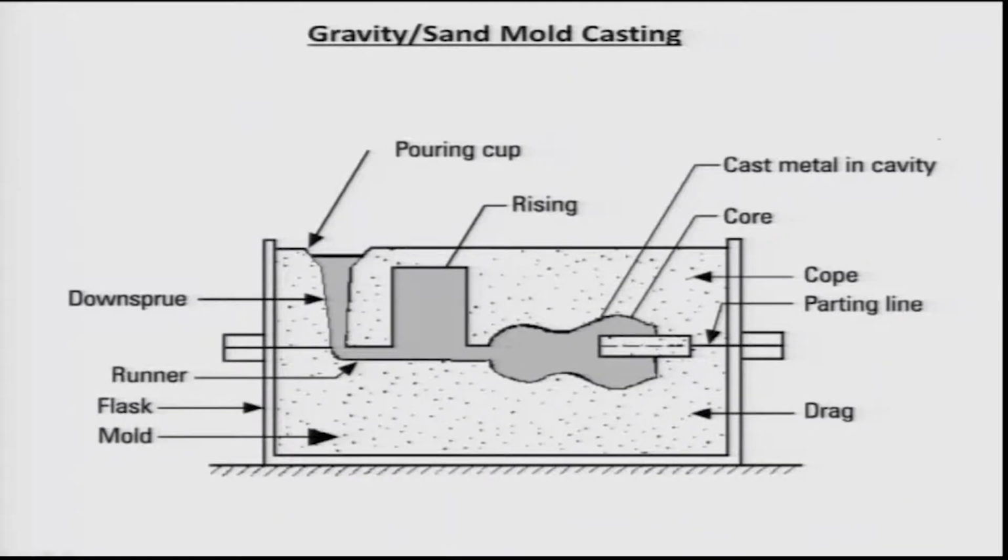Well, I do not want to give a complete lecture on how castings are made, that is a different course altogether. But let me tell you the basic important aspects. The liquid which is poured in the pouring cup travels to the cavity and then starts solidifying. Because of the sand mold, the walls of sand act as heterogeneous nucleation sites.